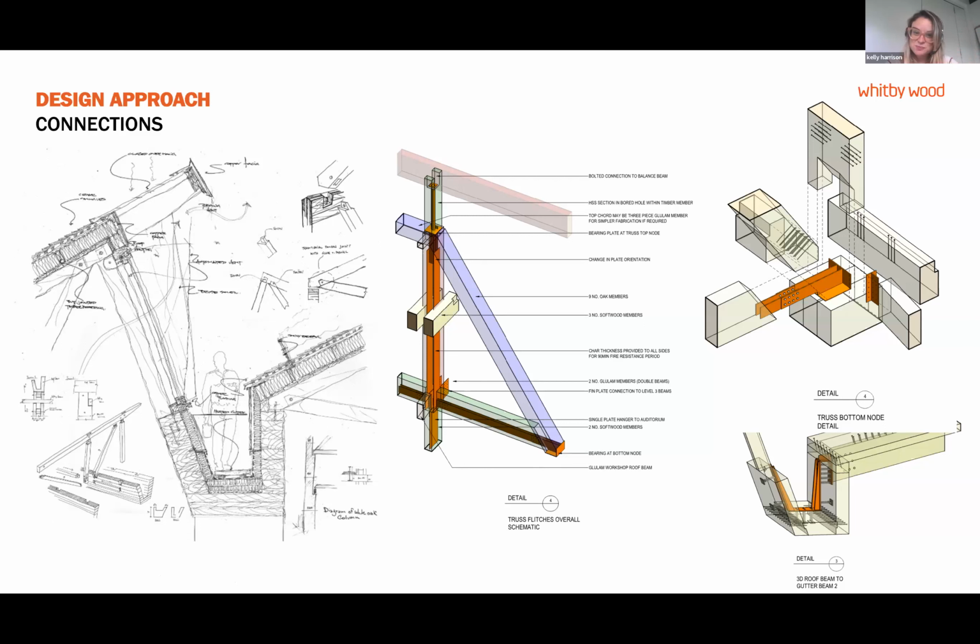What was in just pure bearing, what needed some tensile capacity, what needed ductility, where we needed to add steel to its most effectiveness. And again, that really led the geometry of the whole sort of truss in this case, but also then that led on to the geometry of the roof, and then that led on to the different buildings. So we worked through that as a design team to get the right solution.